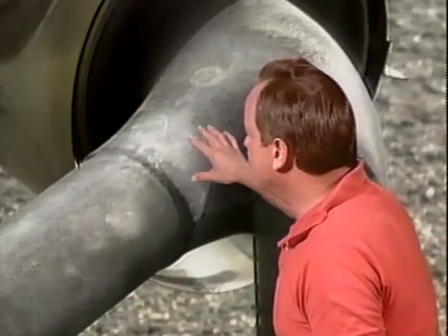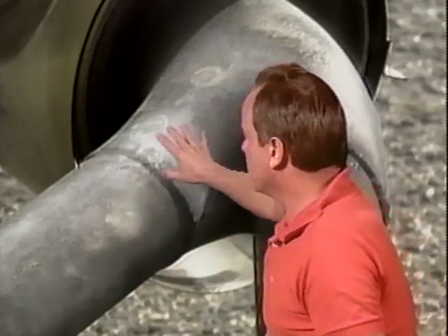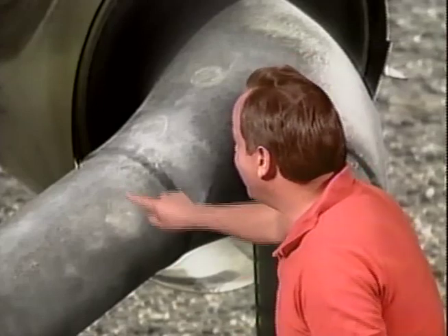Because of the corrosive gas going through here, because of the tremendous heat, the corrosion-resistant qualities of the exhaust system metal are very important. Now, by the way, this is the same type of problem that you have if you use galvanized or zinc-plated tools. You don't want to do that on an exhaust system. Or if you mark the exhaust system with a lead pencil. If you mark this with a lead pencil, the corrosion can form right at that particular spot.